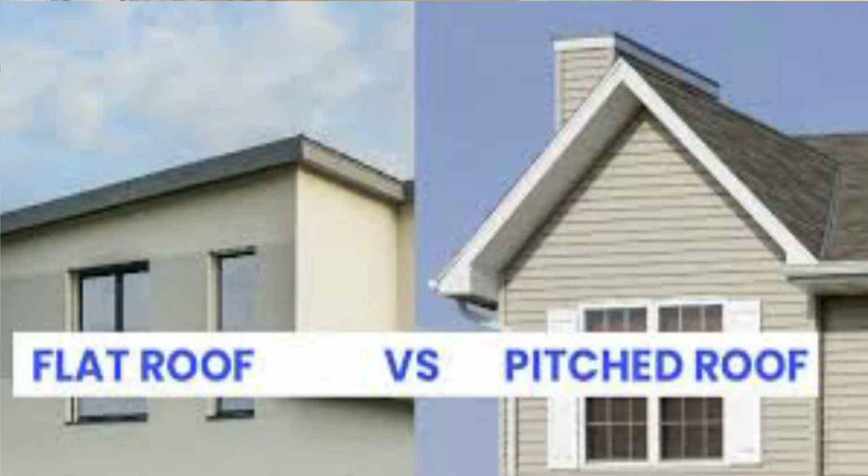Don't forget to do the waterproofing on the top slab because it saves you from leakage and damages in the future. Waterproofing should be done along with the final casting, roof slab casting. So that is the structure. Then comes the beautification part. It includes plastering, flooring, painting, and all other detailing that gives your home a unique character. So a smooth finish ensures the beauty as well as it protects your home from weathering and moisture.